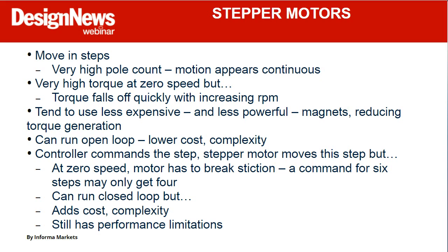And you're adding cost and complexity. You're going to get better performance, but you have certain limitations. So if you're looking for lower cost, something where you've got a little bit of a forgiving application, again, a pump is a perfect example, then a stepper might be the way you want to go.